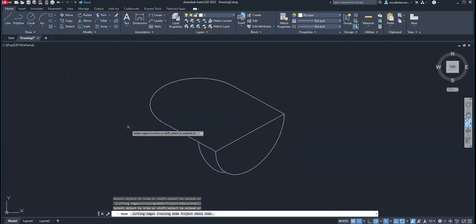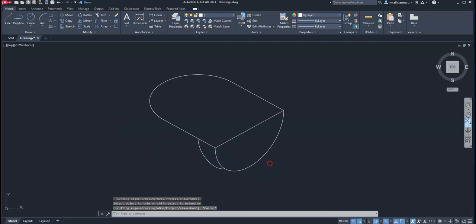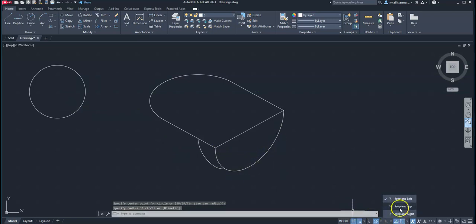But if I only had the orthographic view open, if I go to ISO draft, it asks how do you want to draw? And I hit O for orthographic, it's going to go right back to giving me the normal cursor, and this is the kind of circle that I would get. IsoCircles allow us to sketch on these isoplanes, and there are 3 isoplanes: left, top and right. So this has been a video for how to go about setting up your isometric grid settings, and also on how to go about sketching IsoCircles in AutoCAD.